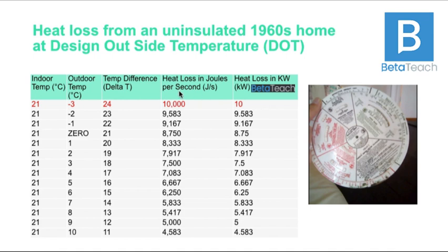Now, when I say speed, we're all used to this thing here, aren't we? Kilowatts, watts. We're used to that term. Now, watts has time built into it. So 1 watt is 1 joule of heat per second. 1 joule of heat moving per second. 1 kilowatt is 1 kilojoule of heat per second. Now you could say it another way. You could say 1 kilowatt is 1,000 joules of heat per second.